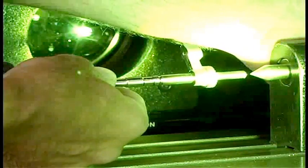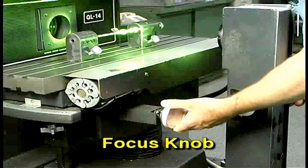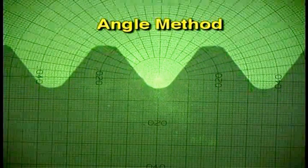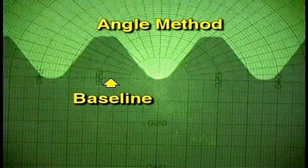Mount the workpiece to the stage and position the threaded portion in the light beam. Focus the light to create a sharp image on the screen using the focus knob. One accurate way to measure the root radius is called the angle method. First, align the bottom of the root with the baseline of the chart.